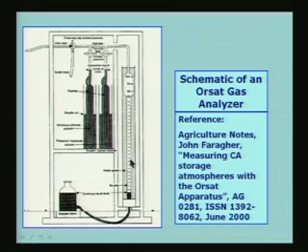So, this will give you an idea about how much is the carbon dioxide percentage by volume and how much is the percentage of oxygen by volume, all at a constant temperature, because this entire thing is going to be surrounded by a water jacket at a constant temperature. So, at constant temperature, the percentage by volume will also be the molar percentage, as we already know. So, it is a very simple instrument, and let us look at what are the possibilities.